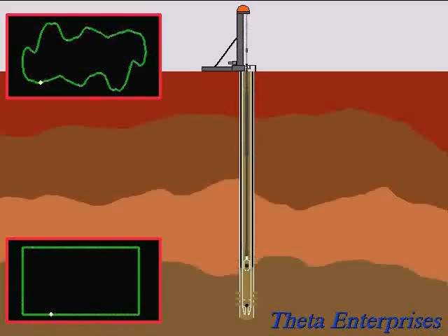The Rotaflex pumping unit, when it picks up the load, puts a big shock loading into the system. And you can see that here in the surface card. When it picks up the load, there is a big increase in load. And that creates a wave that moves up and down through the rod string, and as that wave reaches the plunger, it makes the plunger either slow down or speed up. So that's why the movement of the plunger is not as smooth as you might think. It kind of speeds up and slows down.